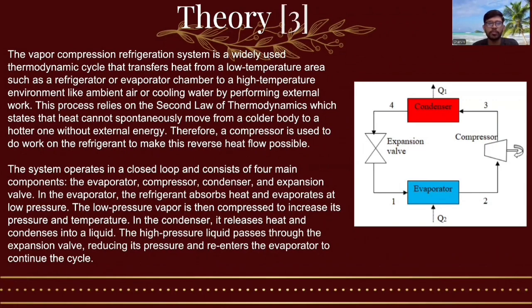For the theory part, the vapor compression refrigeration system is a widely used thermodynamic cycle that transfers heat from a low temperature area such as a refrigerator or evaporator chamber to a high temperature environment like ambient air or cooling water by performing external work. This process relies on the second law of thermodynamics, which states that heat cannot spontaneously move from a colder body to a hotter one without external energy. Therefore, a compressor is used to do work on the refrigerant to make this reverse heat flow possible.